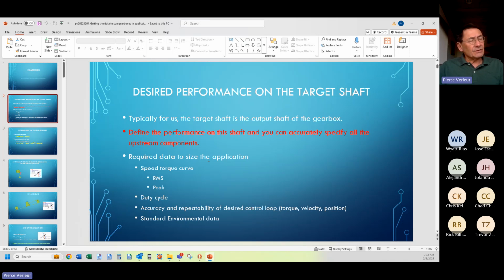Another example to illustrate accuracy and repeatability is if you're shooting at a round target with a rifle, and the center of the target is the measure of accuracy. And the closer you get to that center of the target, the more accurate you are. However, if you're a good shooter, but your scope may be off a little bit, and you group your bullets 4 inches to the right of the center of the target, you have bad accuracy. But if those bullets are grouped within 1/4 of an inch, then you have good repeatability.